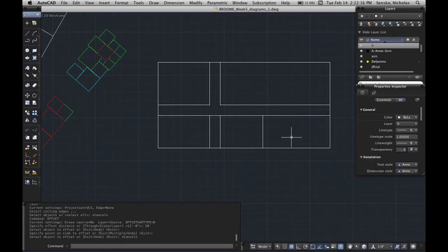But okay, so for your schematic design, a lot of you guys I think are at this point where, so that's one technique, is to take a shape and subdivide it and just use offset to find the dimensions of things. And it's just about projecting things off each other. And this is actually good for circulation, right? Because let's say you take the whole volume of your building, and you know the rough volume of it, but you don't know what your circulation is. You know the big volume, and you know the interior stuff. So what's left over might become what your hallways are.